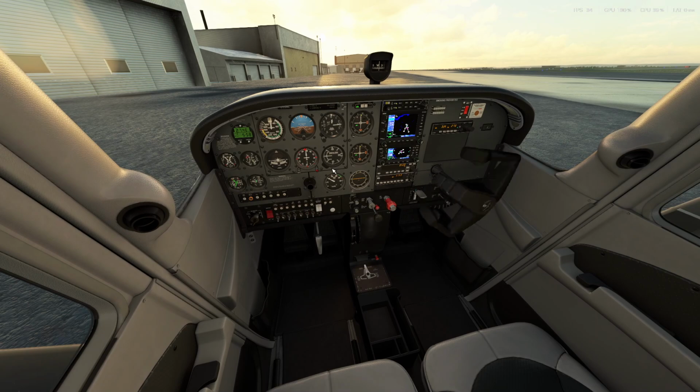Flight controls. Full left, full right, full left, full forward. Flight controls check free. Wind direction confirmed. So when we taxi out to runway 29, there's a wind sock out there, so we'll go ahead and check the winds just to make sure and verify the right direction. Radio set frequency and transmit, so we're not going to be using the radios today. Taxi route,